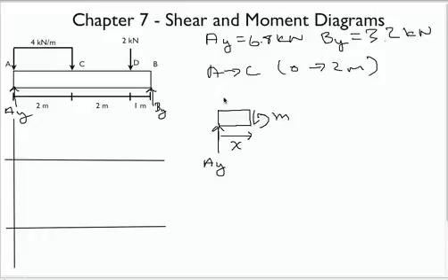And then our 4 kilonewton per meter force. Okay, we have always said just draw the unknown force and assume it in some direction. And we've never really told you you need to always assume that force X, B, or Y, or whatever is in this particular direction. For shear and moment diagrams, and this is really the only place in statics where we're going to do this, well, with the exception of friction that we'll talk about later, but for just general free body diagrams, shear and moment diagrams are the only place where we're going to tell you there is a sign convention.